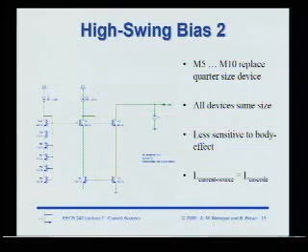But the nice things about these circuits are, first of all, you're using long channel transistors because there's a good reason to do it, to get the high output impedance. That means that square law is pretty much valid here. You're not too far off using square law theory. And what you're really doing is, you don't need a precise voltage, right? It doesn't need to be exactly VT plus 2V overdrive. In fact, you'd be dumb to do that. You're going to have some margin.